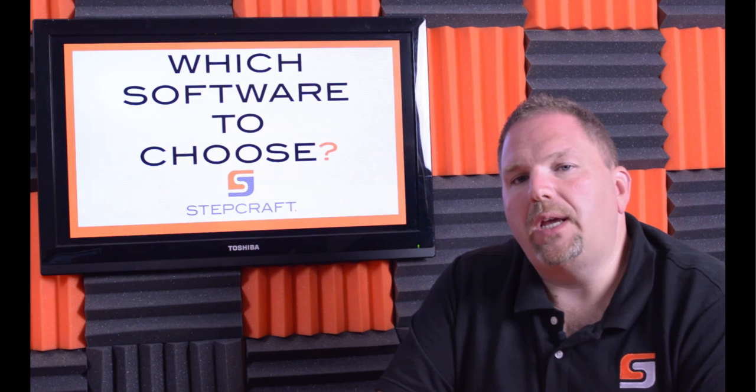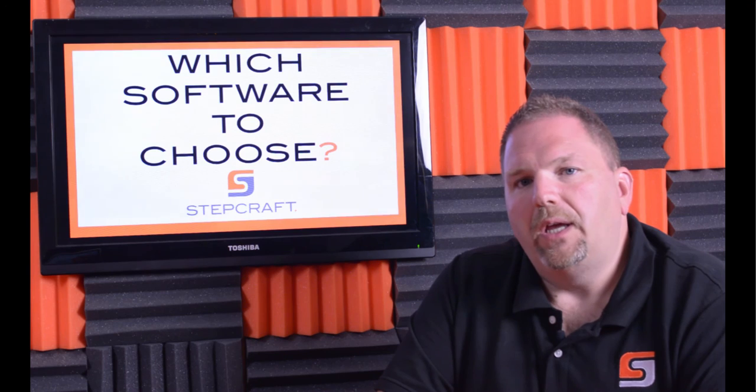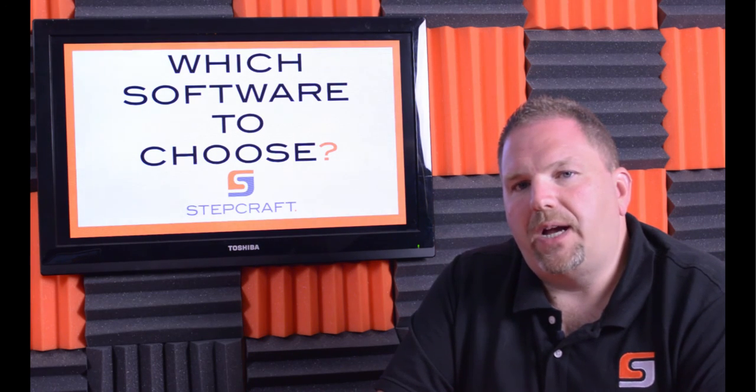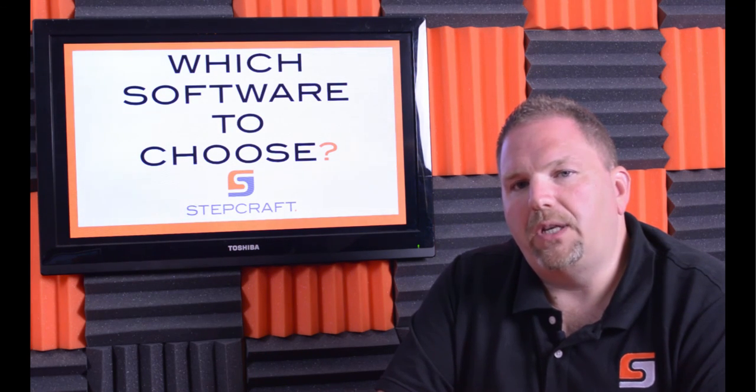In summary, Cut2D is a great program if you're looking to do 2 and 2.5D cutting, milling, as well as pocketing and hole drilling. However, if you're looking to also utilize your machine to do 3D carving as well, then you should take a look at VCarve Desktop. Whether you go with VCarve Desktop or VCarve Pro is largely up to you. Understand that VCarve Desktop has a size limitation of 24 by 24 inches. If you do decide to purchase the STEPCRAFT 840, you need to know that you will not be able to utilize the entire working bed with the desktop version of the software. However, you can tile a job into 2 files to make that work.